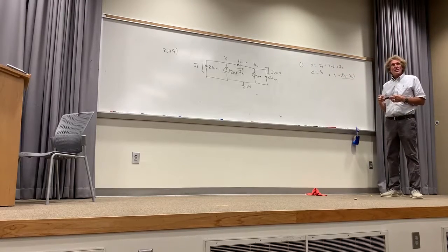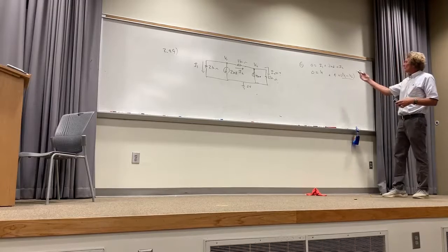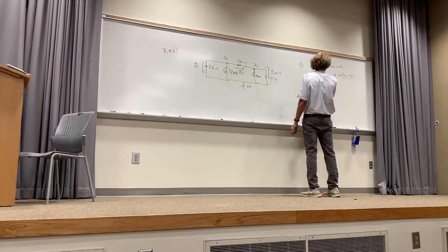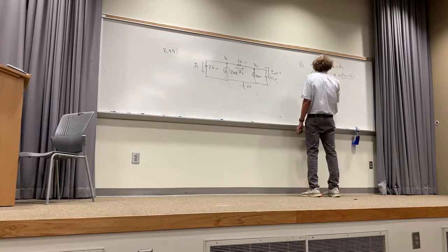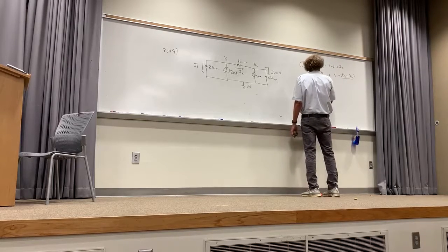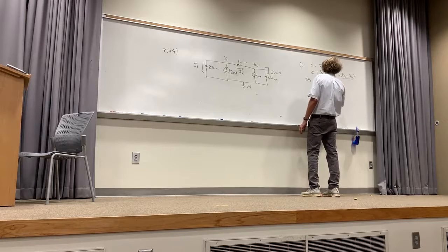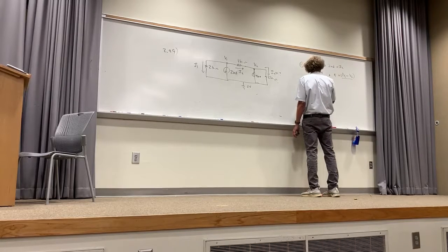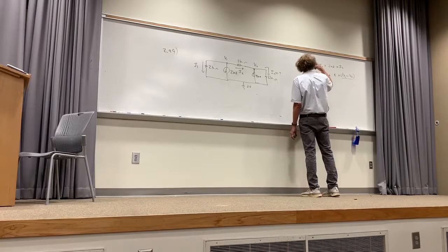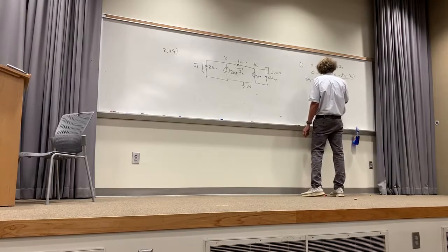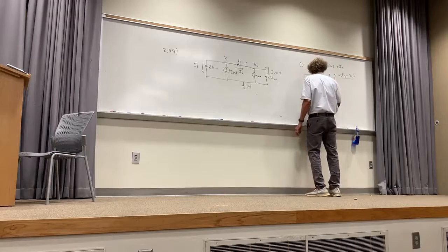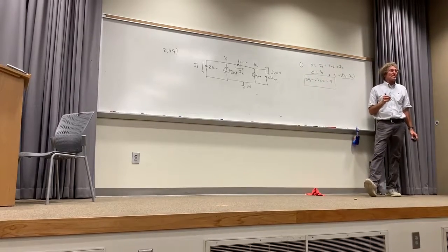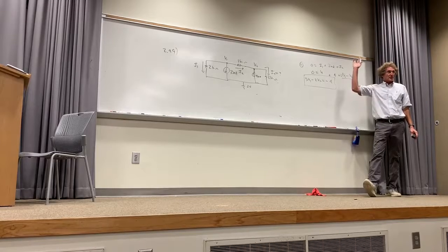Now we're going to get one equation with 2 unknowns. I'll collect the coefficients on V1. Here I have 1 plus 2, or 3V1. Then I collect the coefficients on V2. It's 2 with a minus sign, minus 2V2. That would be equal to, taking the 4 to the other side, minus 4. Take a careful look at that. There's no trickery here. I'm just organizing in terms of something I can put into a matrix. How many see this right here?